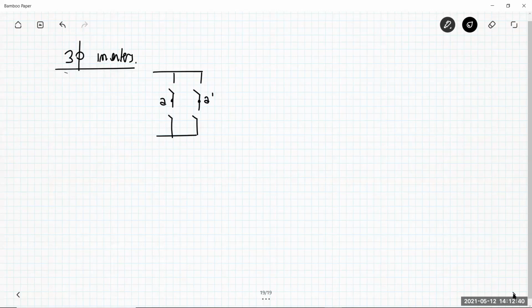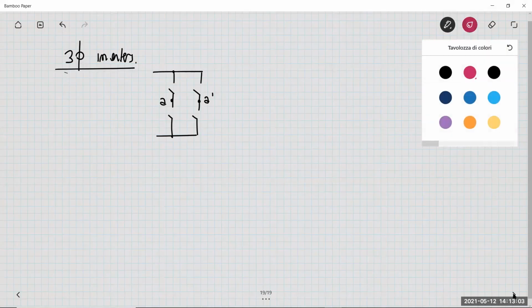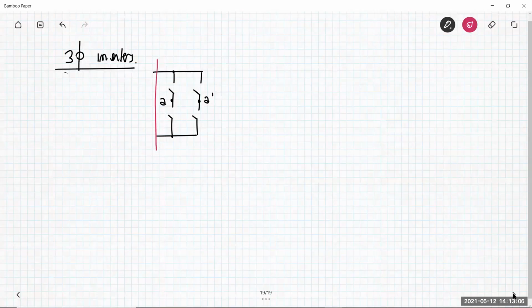Forgive me for this discussion. Let me put a very ideal schematic for the inverter, just the two legs with ideal switches and no diode, but you should understand that switches are transistors, and then you have also the body diode across. The nodes here are A and A prime. So I have a block here, which is the inverter number A, in which you have two outputs that are A and A prime. And so you have here a voltage VAA prime.